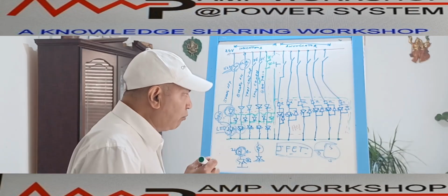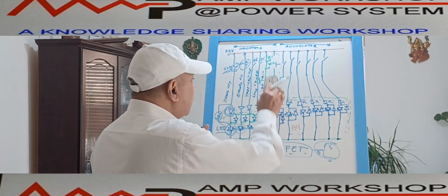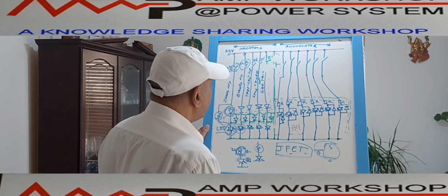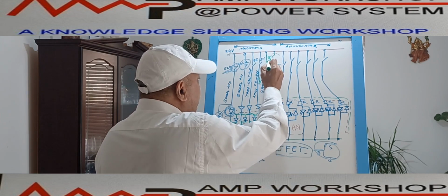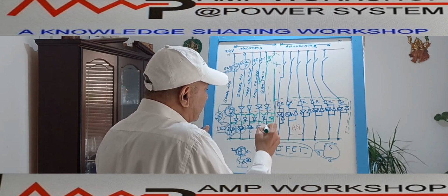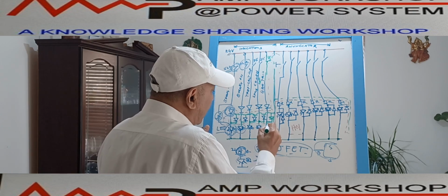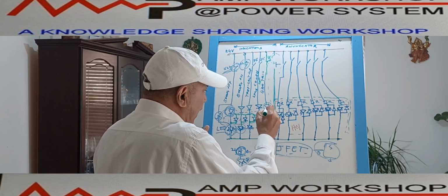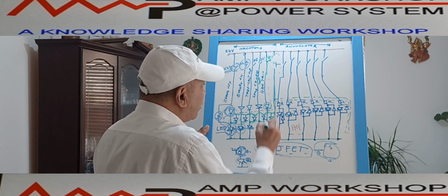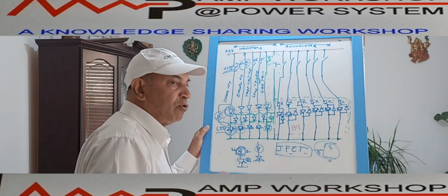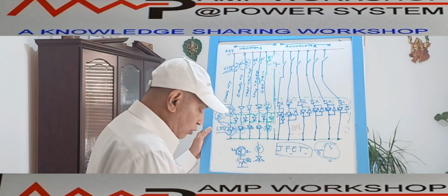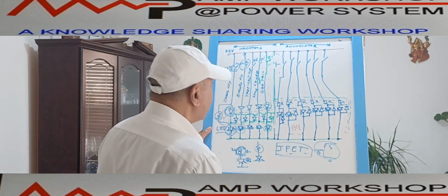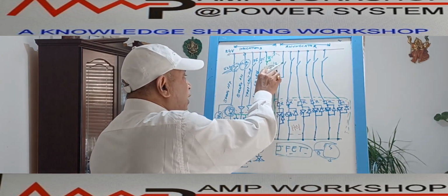If we use only one lockout relay, we have only one NC contact, used in this way. This NC contact allows the current signal to pass through to the lamp. So this is your current drive module, and the current passes through the LED, so we get this lamp. But if we use multiple lockout relays, then their NC contacts have to be connected in series. We have to keep that in mind.